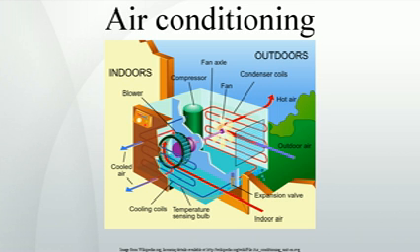in the winter. The icing problem becomes much more severe with lower outdoor temperatures, so heat pumps are commonly installed in tandem with a more conventional form of heating, such as a natural gas or oil furnace, which is used instead of the heat pump during harsher winter temperatures. In this case, the heat pump is used efficiently during the milder temperatures, and the system is switched to the conventional heat source when the outdoor temperature is lower. It also works on the basis of the Carnot cycle.